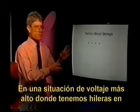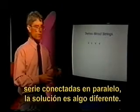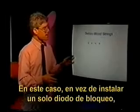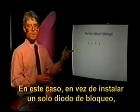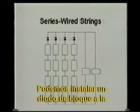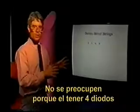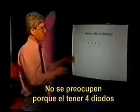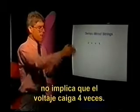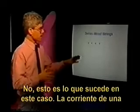In a higher voltage situation where we have series strings wired in parallel, we have a slightly different solution. In this case, instead of installing just one blocking diode, we have a different option now. We can install a blocking diode at the head of every series string. Don't be concerned. A lot of people get confused and think, well, I've got 4 diodes now, so I've got 4 times that voltage drop. No. This is what's happening in this case.